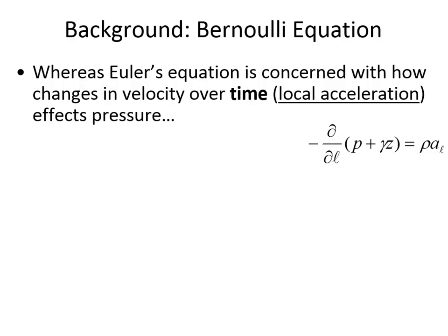the pressure itself, or it could be the elevation of the water surface above some datum. And so in the two different kinds of problems we worked, we'd have maybe an enclosed tank of water that was accelerating in some direction, and we compared how the pressure was different between 2 points as it accelerated to the side. In an enclosed tank, the water elevation couldn't change, but the pressure did change. If the tank is open to the atmosphere and you start to accelerate it, then the water surface changes. The pressure is still going to be different between 1 and 2, but the water surface is going to change as well. Euler's equation is what we use to characterize the effect of local acceleration.